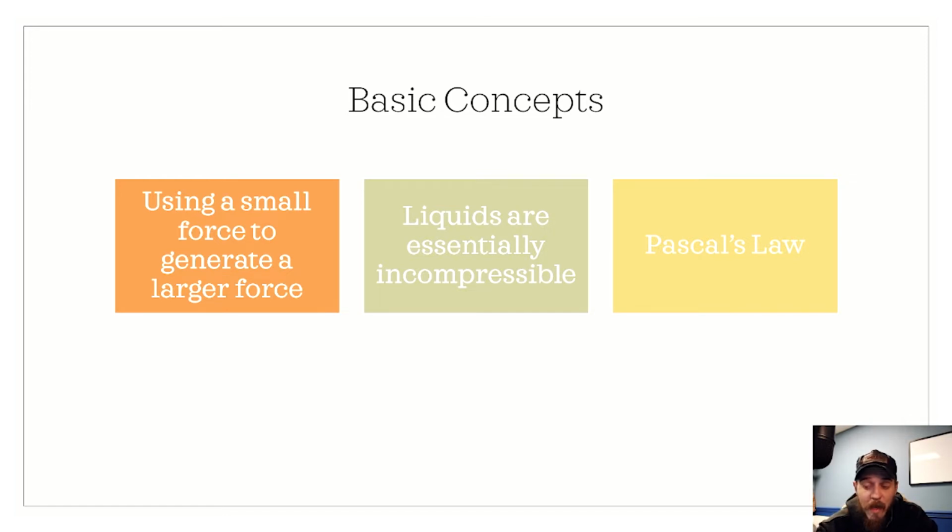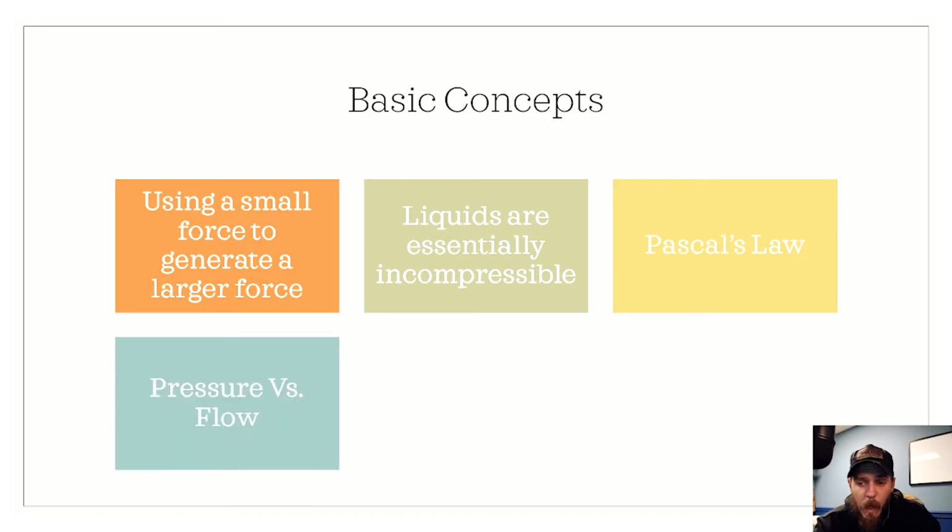We have to understand the basics of Pascal's Law, just the same way we have to understand the basics of Ohm's Law, Kirchhoff's Law, Boyle's Law. We don't need to know every single theoretical mathematical equation. We just need to understand enough of it to be able to apply that to what we're trying to do. We need to understand the difference between pressure versus flow and how they are generally inversely proportional. As pressure increases, flow generally decreases, and vice versa. There are exceptions to the rule, as there are exceptions to pretty much every rule, but in general, pressure increase, flow decrease.